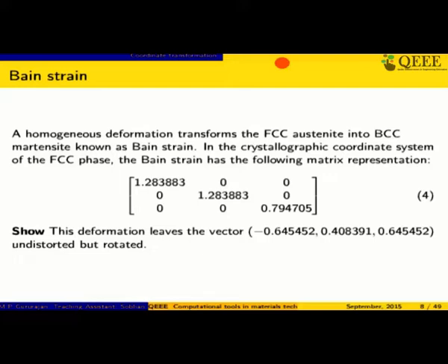So this is a non-equilibrium phase that comes about when you cool the material very fast. So what happens is, when you cool the material, it is not having time to change into the other crystal structure that it would prefer to have, which would reduce its free energy. So thermodynamically, that is the most stable state, but for kinetic reasons it's not able to go there. There is no nucleation, there is no growth.